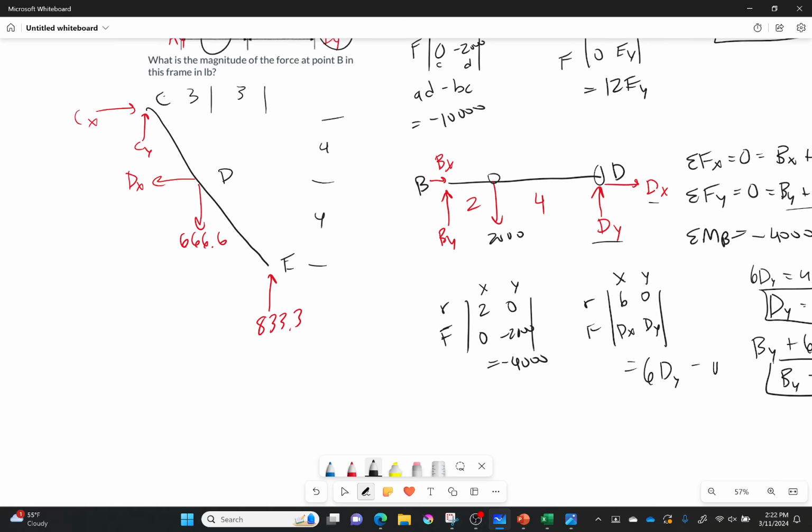Now, we've done that. The hardest part was just remembering to change the direction of your arrows. Everything else is going to go really, really easily now. So let's write out our three equations again, because every single free body diagram gets these: some of the forces in the X, some of the forces in the Y, some of the moments around a point I'm going to choose.